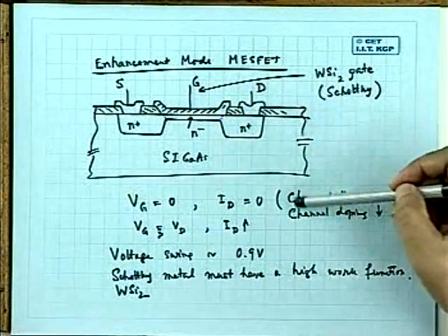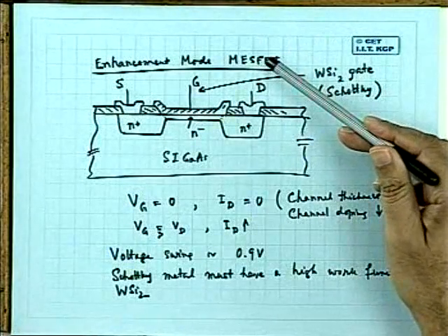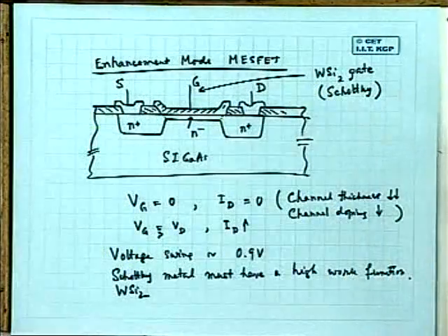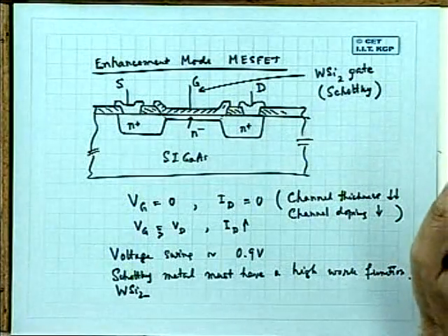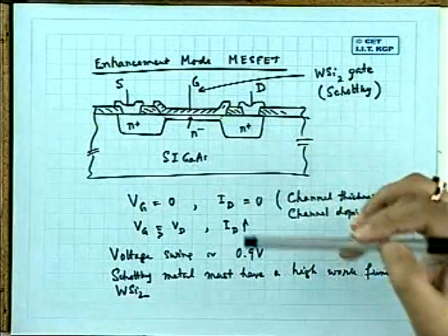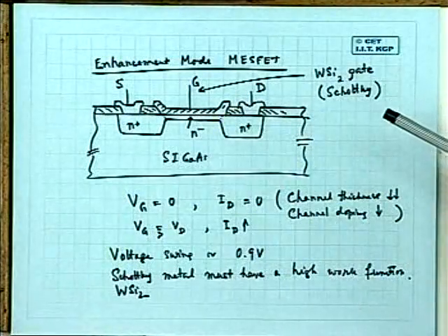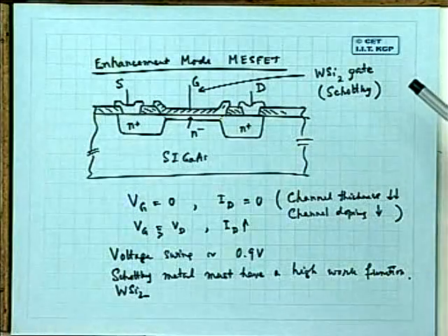This kind of devices, the MESFETs, which are normally depletion mode type, work very well under depletion mode condition. Enhancement mode is required for circuit requirements, which I have repeatedly told you. Driver should be enhancement mode device. Therefore, modern MESFET logic, called GaAs logic, is normally used for special optical amplifiers, in the front end of the modulation circuit of fiber optic amplifiers, fiber optic control circuits, and different other applications.